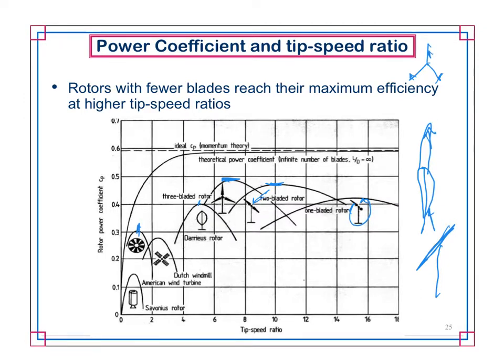So it has the best case characteristics in terms of longer lasting design, because having a tower that does this, because it's going to be tilting, it's very hard on the blades, it's hard on the bearings, there's a lot of issues with maintenance like that, where this one doesn't have the same set of issues. This one over here doesn't have the same set of issues with torque because, again, you have so many blades it doesn't really matter. But that's why we have standardized on 3 blades. You do see on occasion 2-blade ones, but they're not that common. Those would be like very high wind speed applications, and I've never personally seen a single one.